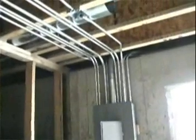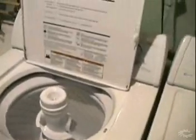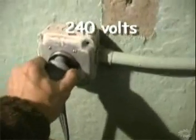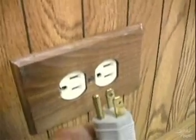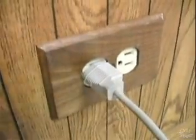After the electric wires go into the electric meter, they go into the building's circuit box. This box then provides a series of separate circuits for the electric current to flow through. For instance, the clothes washer and dryer will probably need greater push to do the kind of electrical work they are designed to accomplish, so a special 240-volt circuit is set up for those electrical devices. Notice the plug for the clothes washer is different from other plugs. Other circuits in the home will need typical 120-volt connections and outlets. So circuits are set up to run into different parts of the home to prevent one circuit from becoming overused.